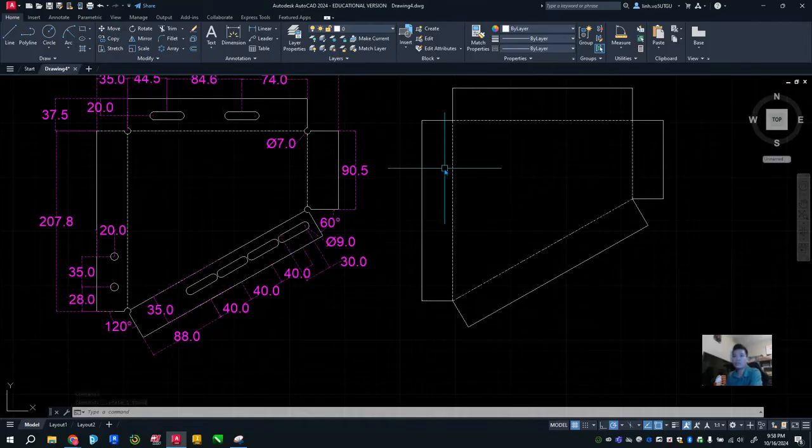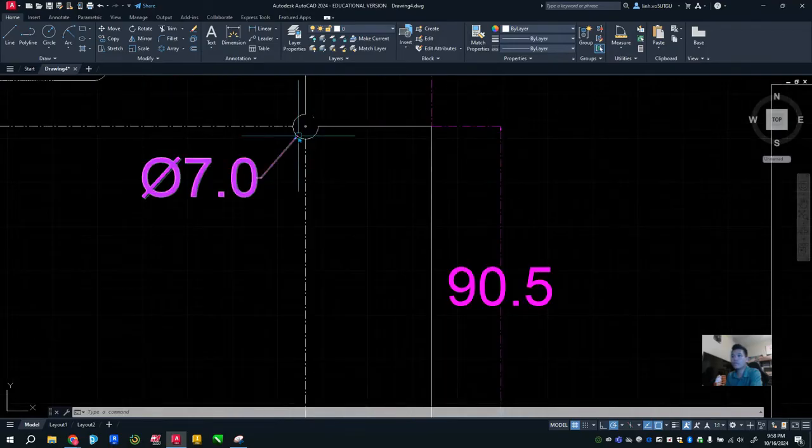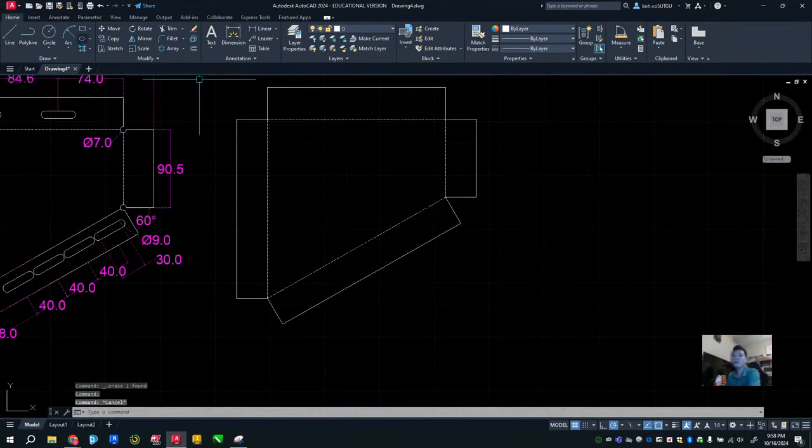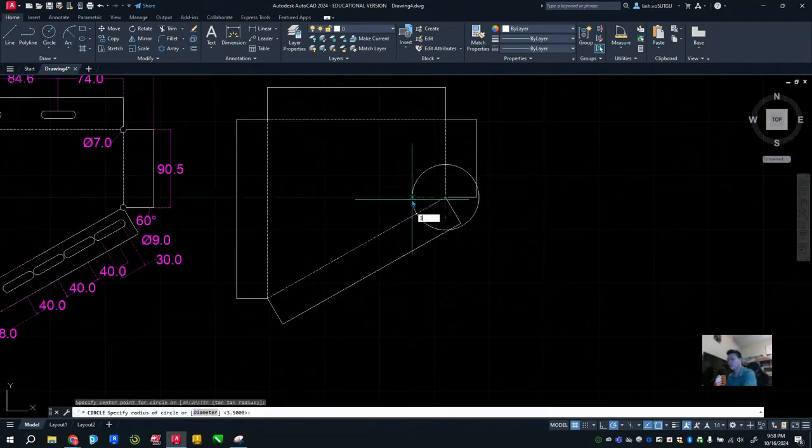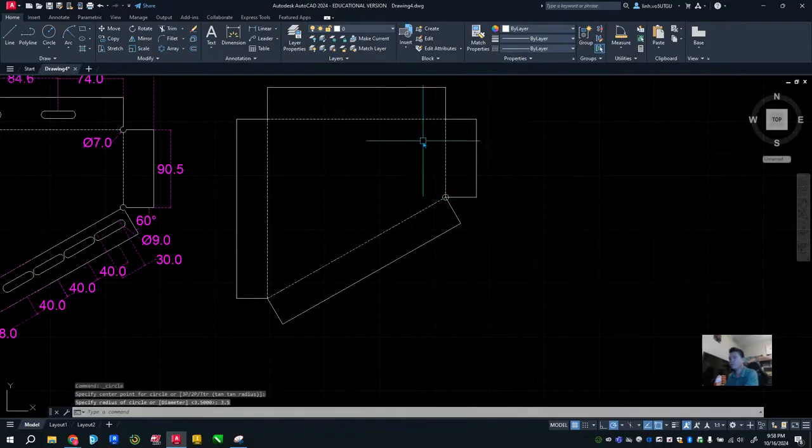And so the thing that we can go do real quick is these four tiny circles in four corners. They have a diameter of 7. So we're going to go ahead and click on it. Here we are. So its radius is going to be 3.5.